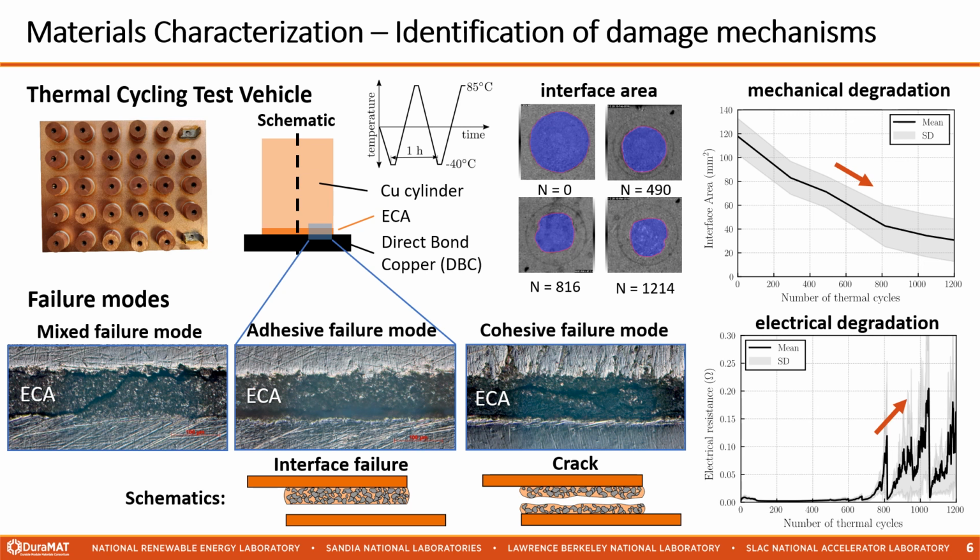We monitored the interface area with acoustic microscopy and detected mechanical degradation in the form of interface area reduction. In addition, we monitored the electrical conductivity and found that with decreasing interface area, the electrical resistance increased.